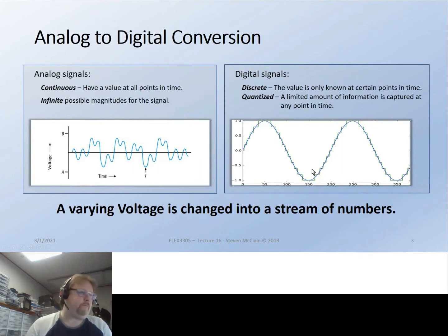I think we're using a 14-bit converter. How many steps is that going to give us? 16,384. So we've got 16,000 steps up and down, and then we can run that at about 100 kilohertz or something if you really let it rip. And that'll tell you how fast of a sine wave you can measure.